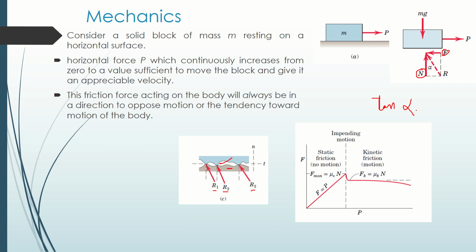As a result, all of a sudden, the object passes through the peak value of the hump or the surface irregularity and starts to move. The moment it climbs that hilltop, that is the place where you have the maximum resistance within the two surfaces. Until that point, your object is in static position. Once it starts moving, your kinetic friction tends to drop suddenly.